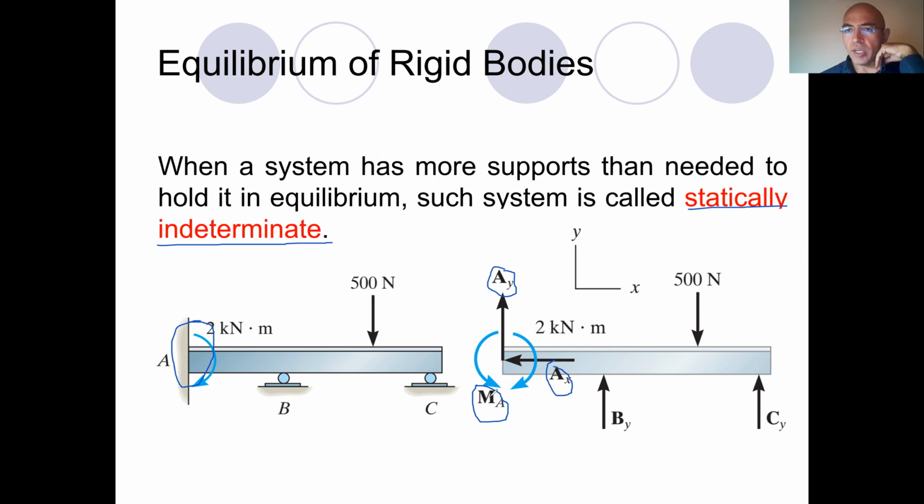and a moment as a support reaction at point A, whereas at point B, if you just isolate the system and just focus on the point B, you can easily see that the object can easily move in the horizontal direction, either to the left or to the right-hand side, but cannot move downwards.